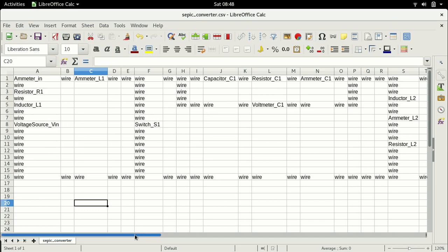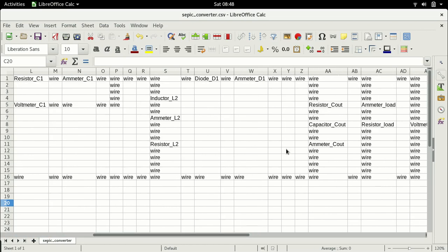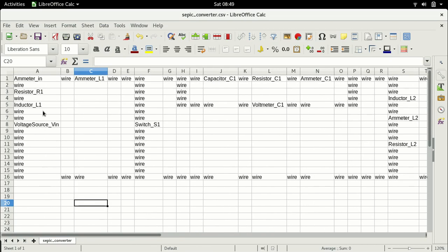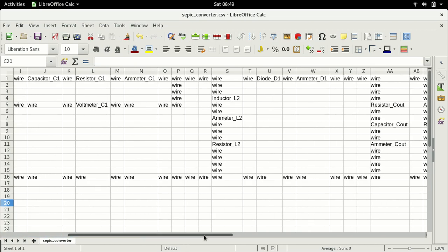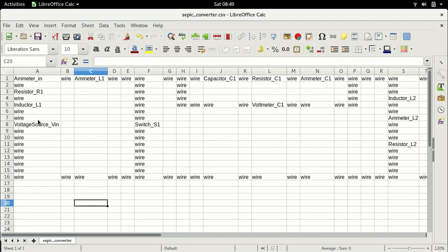So in this forward direction, when the switch is turned off, the voltage source and the inductor charge the capacitor and the output voltage, right? So we have a series path where the voltage source, the inductor, the capacitor all appear in the same forward path. And therefore, in the boost mode as well, even though the output voltage is larger, because we are adding up the energy of the voltage source and the inductor, the capacitor does not have to be at a larger voltage. Capacitor still remains at the same voltage.